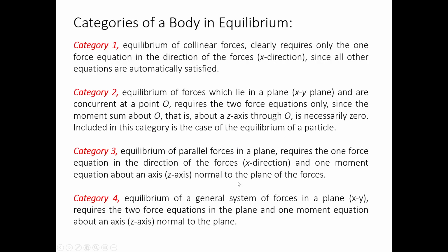Okay, so we have four categories. I think categories 1 and 2 have already been discussed, katong equilibrium of a particle. So we'll proceed to category 3, which is your parallel force systems. This requires one force equation in the direction of the forces. It may not only be the x direction, it may be the y direction as well. And of course, we're going to use one moment equation.